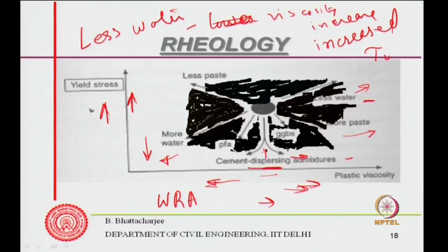The lower the water, the higher both yield shear stress and viscosity. With more water you have lower yield stress and lower viscosity. With less paste, viscosity reduces but the yield shear stress increases.